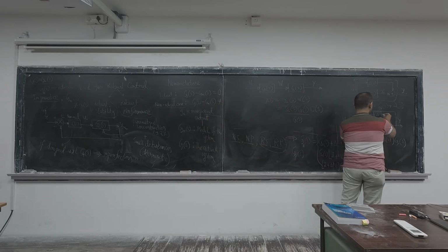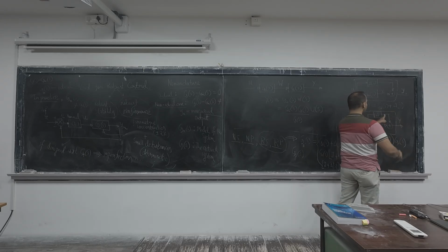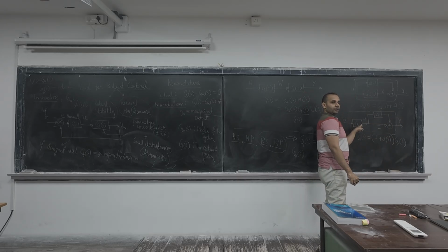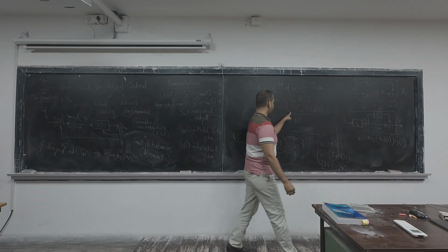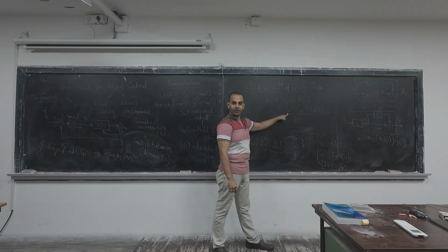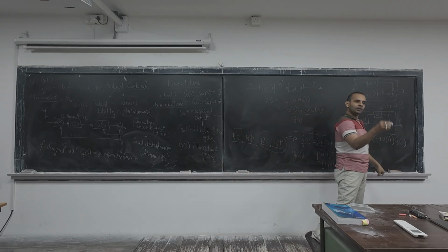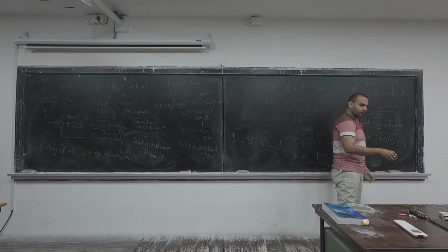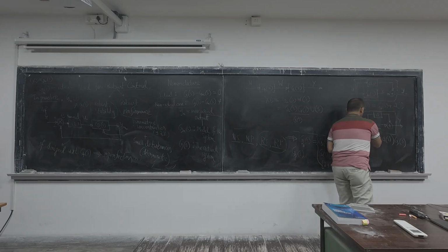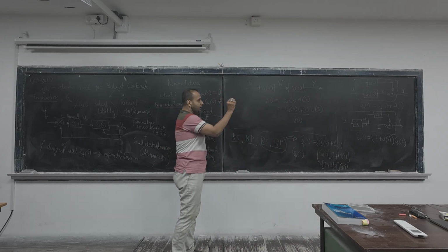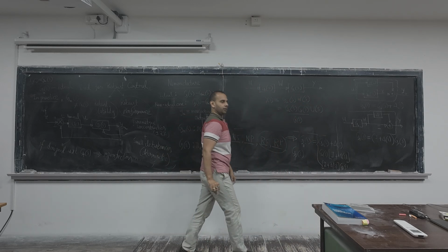Suppose this I plus delta of S, you consider this one as G2 and this is G0. Then as I did here, this block is appearing at the first. So here also I plus delta S will appear at the first, right? So that's why I said that maybe you introduce an intermediate signal and you apply this procedure. Whenever you have a doubt, you do this.